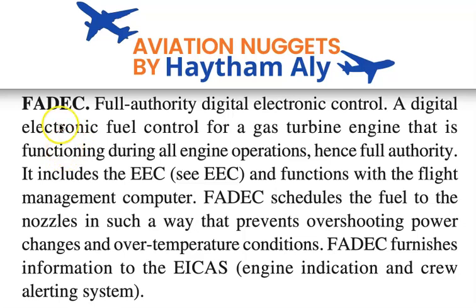So again, if we define the FADEC: full authority digital electronic control. Some other manufacturers call it full authority digital engine control, yes, it is electronic engine control, like engine control by wire. A digital electronic fuel control for a gas turbine engine that is functioning during all engine operation, hence full authority.